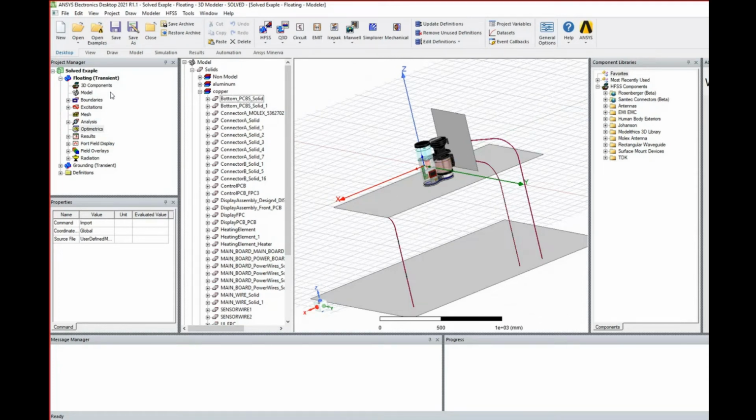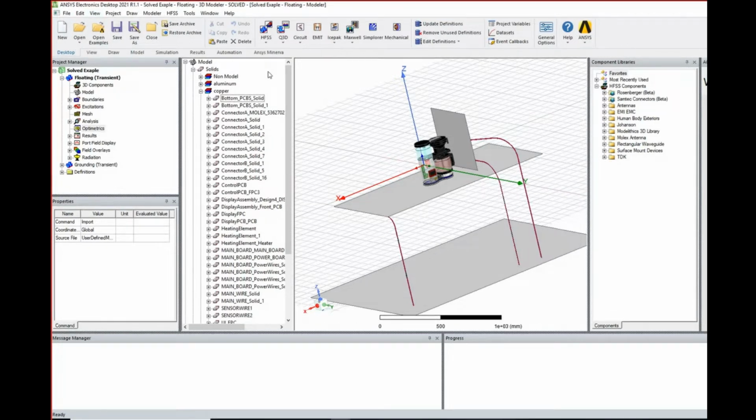You can see the Ansys Electronics Desktop, which includes different tools. In the top ribbon, you can see the list of tools available in the Electronics Desktop. We have HFSS for high frequency applications, and we have HFSS 3D Layout, which is a tool for the layout interface of HFSS. We have the Q3D Extractor and 2D Extractor, which can be used to extract the RLCG parasitics.